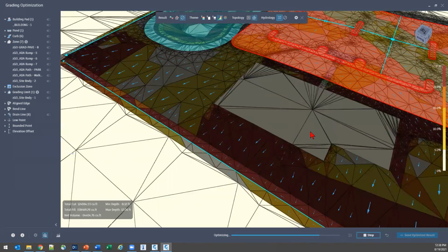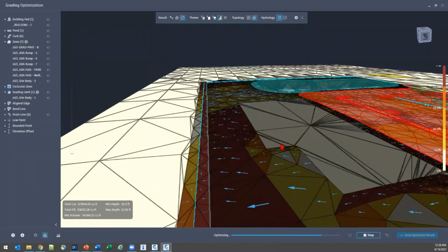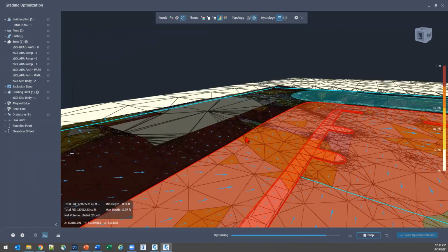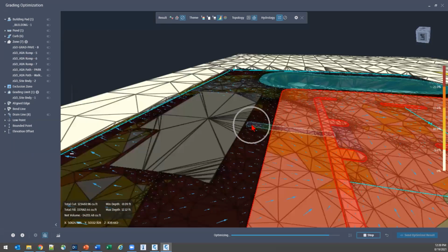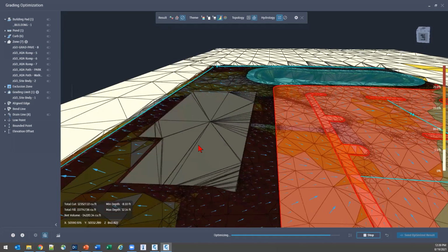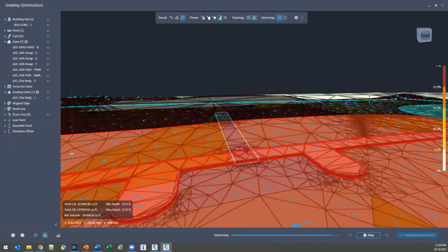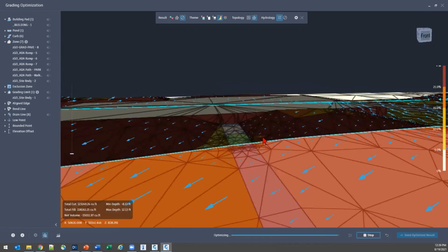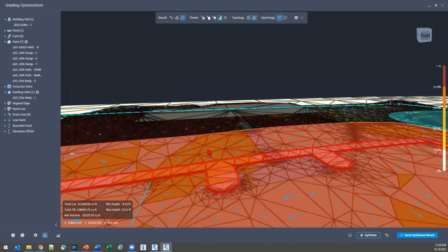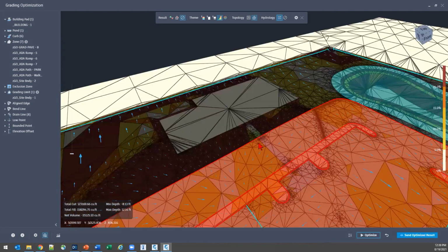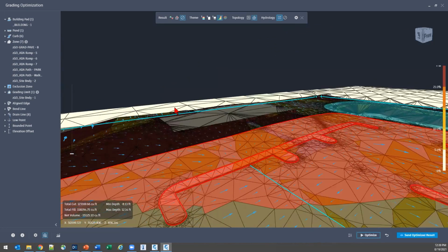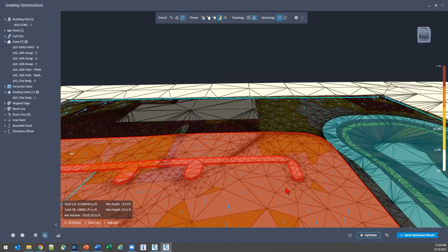I will encourage you to pay attention to your building pad. I had set my practice one up previously as just a standard type zone, and it was having a really hard time making my pathway line up with the actual entrance of the door. And it looks like we are not really respecting that today either. So we'll want to find a way to bring that down, or if we have to force that elevation down later inside Civil 3D, we can. We're just going to have to recalc our earthworks. So either way, looks like we've got a bit of a berm off to the left side of our building. We may want to mitigate that.